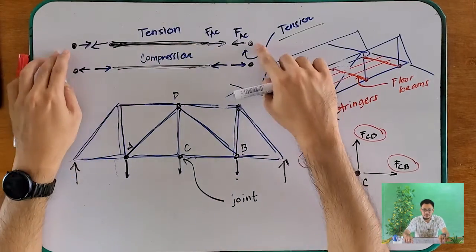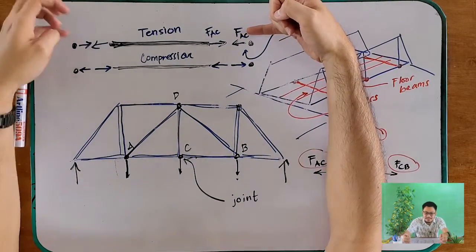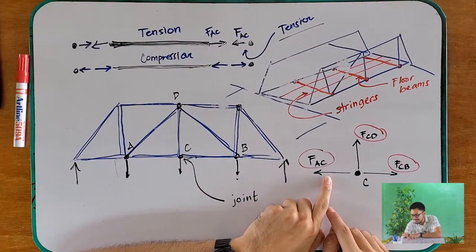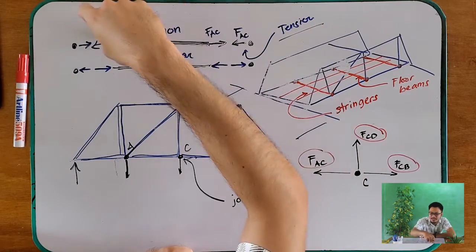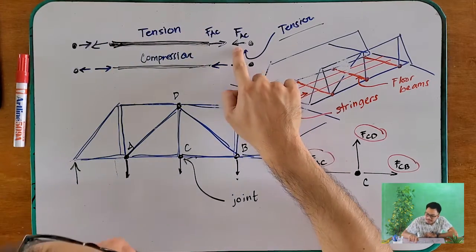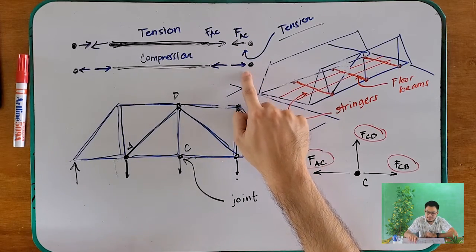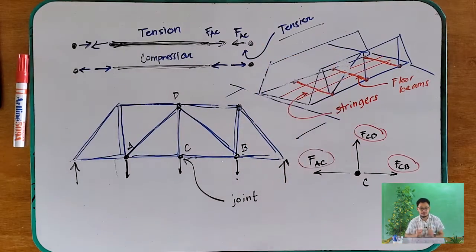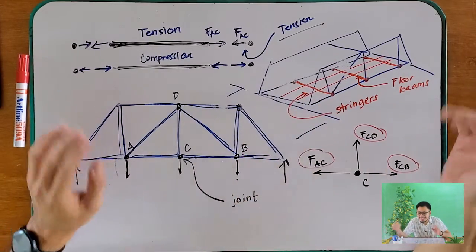So, tension siya. Okay, again, take note. We assume that these forces are only applied at the joints. And if we're going to determine your FAC, then this FAC is actually the force in your member. Okay? And if in ani atong direction, that is in tension, and if in ani atong direction, that is in compression. Padong sa atong joint o pa away sa atong joint. Okay? We'll have an example later on for us to be able to understand this one more.